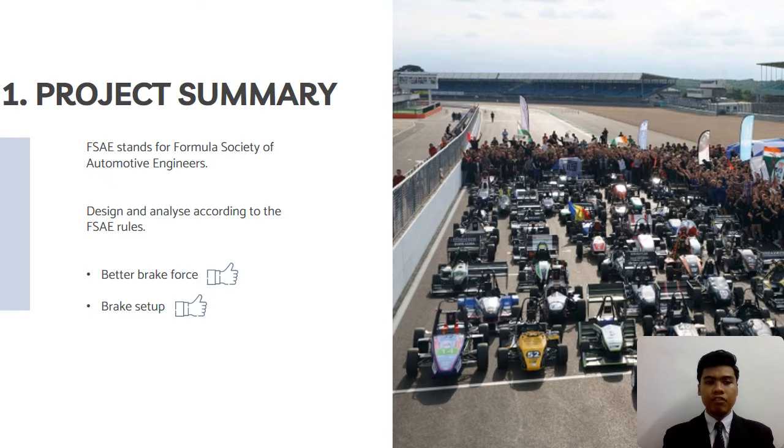FSAE stands for Formula Society of Automotive Engineers. FSAE is a series of international competitions in which university teams compete to design and manufacture the best performing race cars. In this project, the braking system is designed and analyzed according to the rules and regulations laid down by the FSAE, such as the braking system must act on all four wheels, be capable of locking all four wheels, and must have two independent hydraulic circuits.